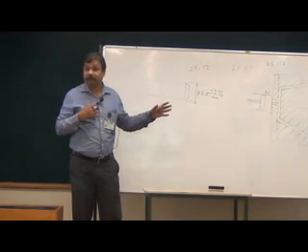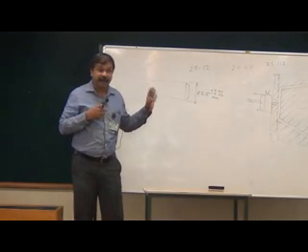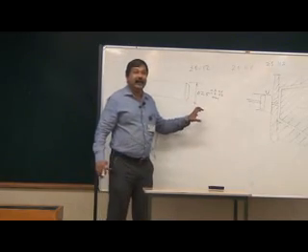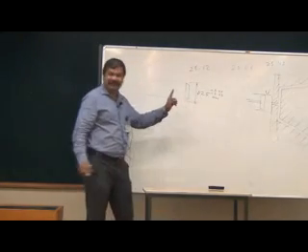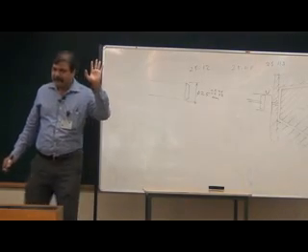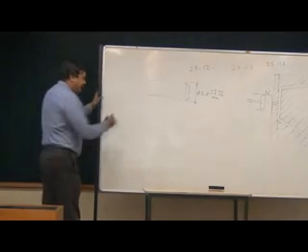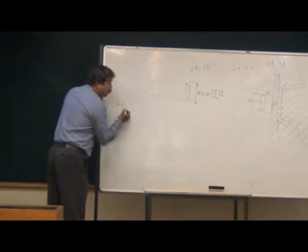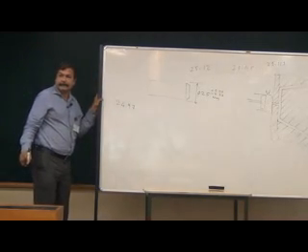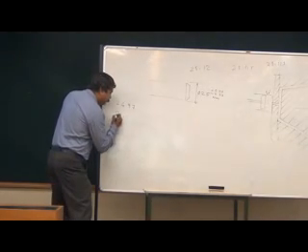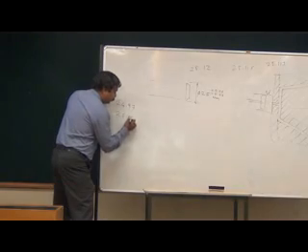For every dimension in my design, I should provide a tolerance band. What is the meaning of this? The diameter can be anything, but it must be more than 24.97 and less than 25.05.